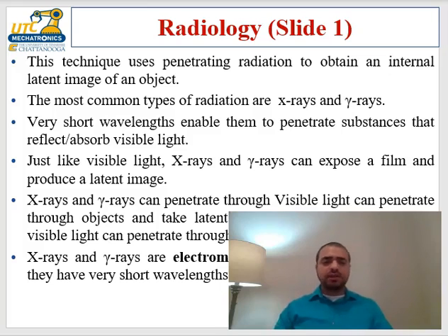X-rays can penetrate through most objects. It depends basically on the density of the object. But typically, X-rays cannot penetrate through metals, so they will reflect from a metal surface. However, if you increase the energy, they can see through some metals, depending on the density and the thickness of the metal. Gamma rays, on the other hand, can penetrate through most metals, even really thick metals.